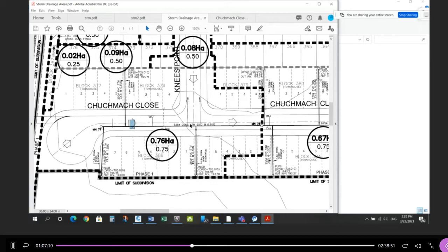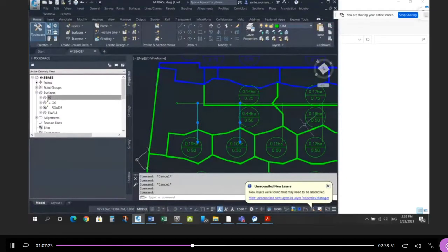In Richmond Hill, you have to show the flow going to this pipe, the flow going to this pipe, and the flow going to this pipe, and the areas for each. That's why I asked you to do it the way I did. So the way we delineated it, one area for each pipe, is what they do in Richmond Hill. Okay? If you start with that, it's easier to combine areas than to try and combine them on the fly, the way that it's finally shown in Milton.